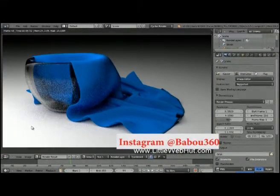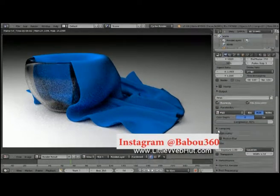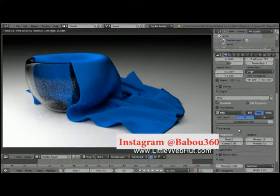Well, everything looks good with this image, so now we're ready to render the final image with more samples. So come down here and open the sampling section. This section is called Integrator in some older versions of Blender. This value sets the number of render samples that would be used. I'm going to increase the value to 2000. The larger this number is, the better the final image will look, but the longer it will take to render.